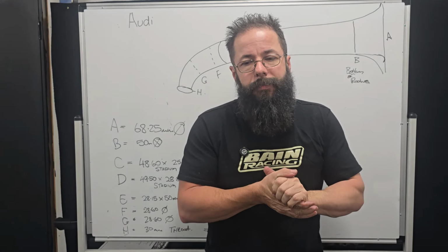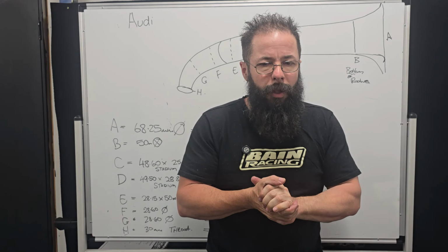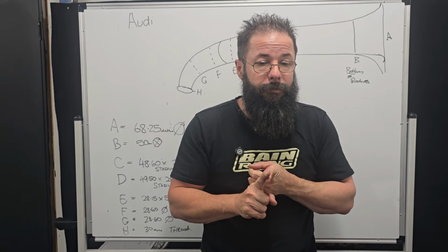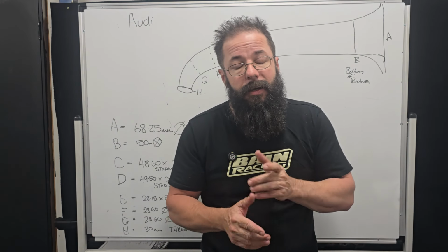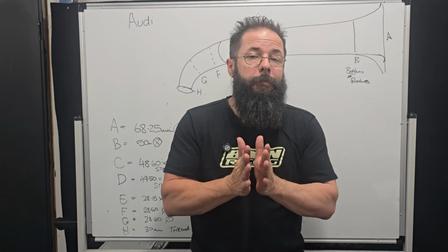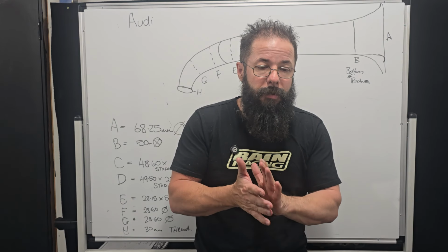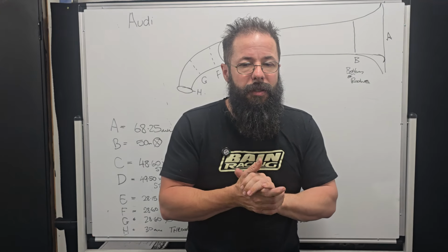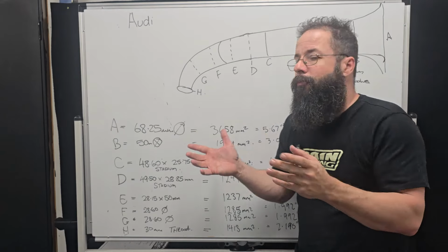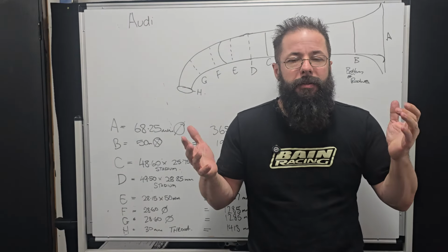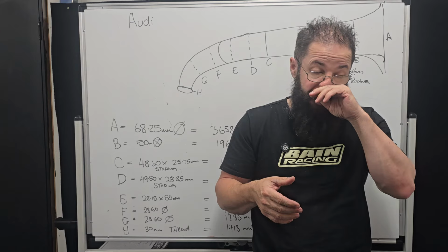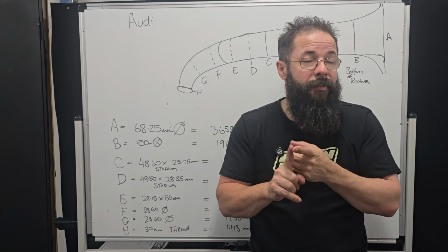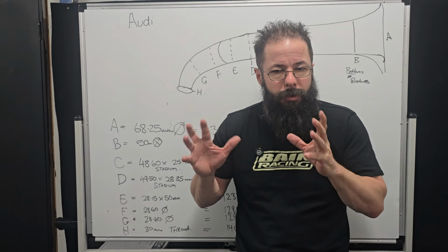I'm going to take some port lengths, induction lengths. We'll work out what our induction length should be for that 8800 RPM. And we'll work out what our minimal cross-sectional area needs to be optimal for this engine at the RPM targets we have. And this will give us a little idea of what we've got to do. But really, really simply, even if you're doing something like this at home, and this is something we've gone through on the Einstein app, looking at the 2J and basically highlighting areas that we definitely don't touch because they're already too big. And this is what it's all about.